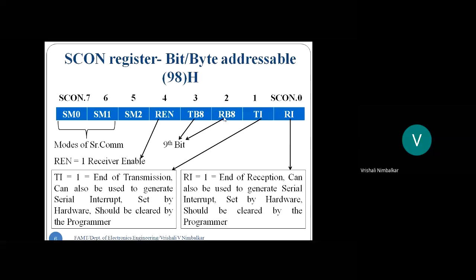If I do not have the parity bit in the UART frame, it means we are transmitting 8-bit data. If I am adding the parity bit, it means now we are transmitting 9-bit data. Apart from the start and the stop bit, the frame inside is of 9 bits. 8 are the data bits, the 9th is the parity bit.